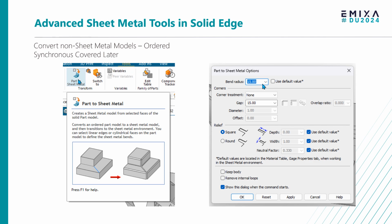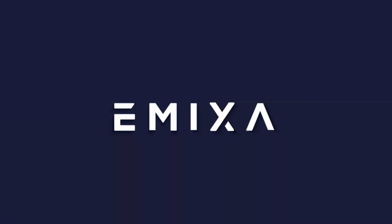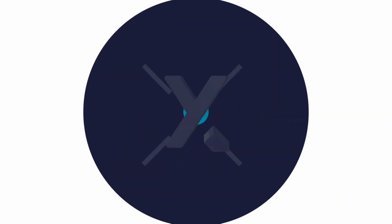So here we can just create a shape that we want, just a square. We can draw lines of where we want the edges to come together, and then we can use this command to turn a basic shape into a sheet metal enclosure almost. So let's have a look at that in action.